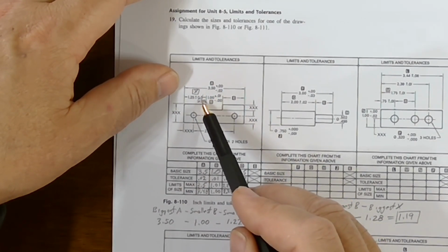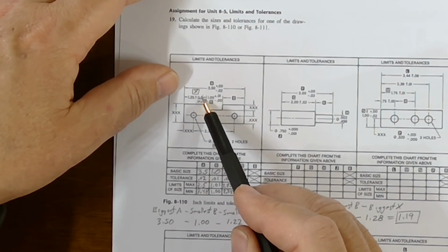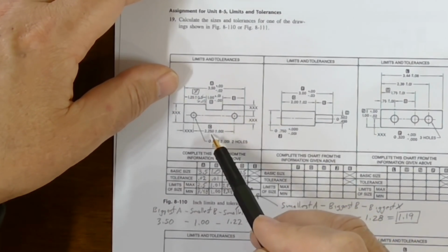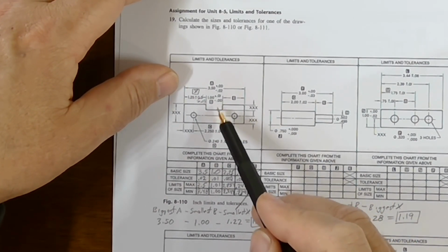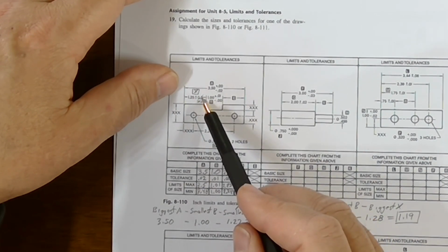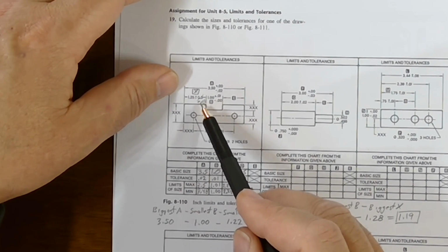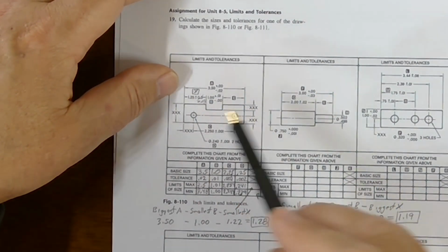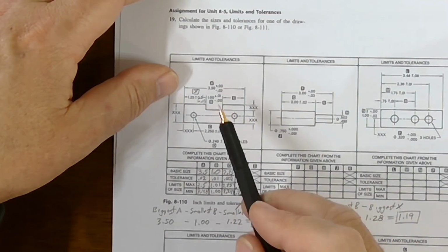Okay, the other thing I changed is look at this here. The tolerance that they're giving you, or the over and under values they're giving you, is 0.3. That's so big compared to these others that it's just crazy, right? Like, if you have to hold these to a high tolerance, but then you can all of a sudden be 0.3 plus and minus, it makes no sense. So it's got to be a typo. So I changed it to 0.03. So there's other typos in here. Change them if they don't make sense.